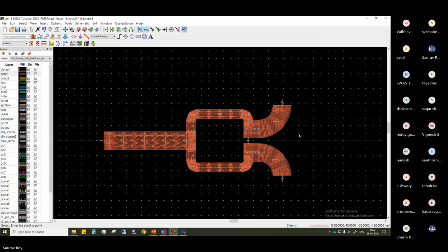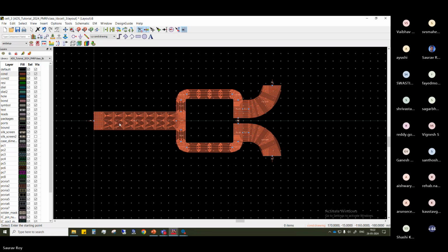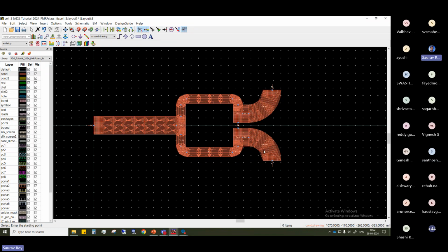now you see, between the two ports, 100 ohms must be there, no? We have to... No, not here. You should listen carefully. I told you in the EM simulation you cannot add lumped components. But in ports we can add, no? Ports, this and this we can add. That we will come to in the core simulation.